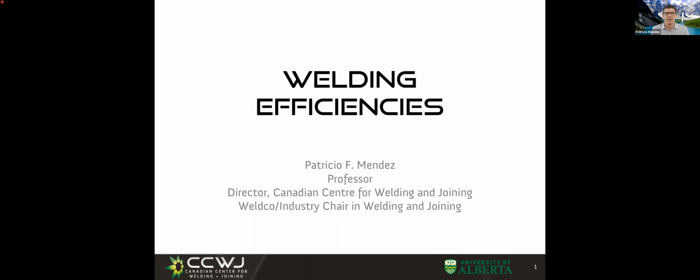Good. We have just talked about mass balances in welding, about how the deposition rate relates to our productivity in having put so much metal in the form of a weld. And I was hinting here and there to efficiencies, right? I talked about the consumable efficiency. At one point, I talked about the metal efficiency, but I was vague. Okay, I'm not vague anymore. Let's talk about this seriously.